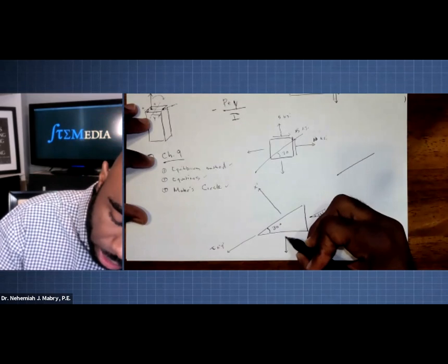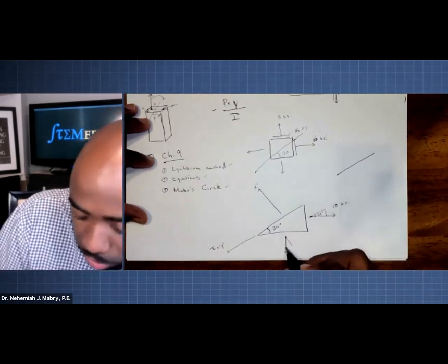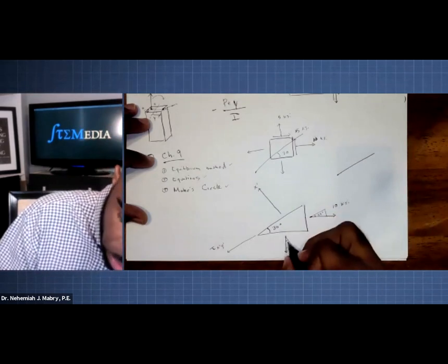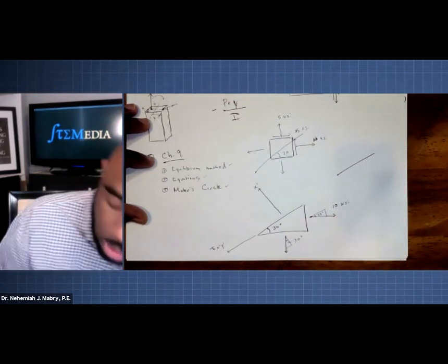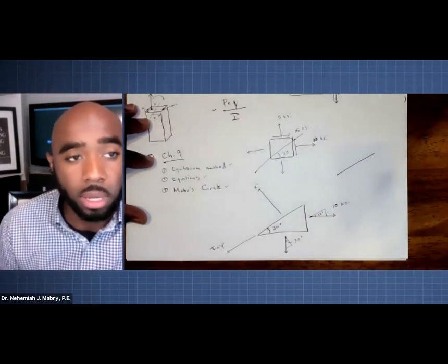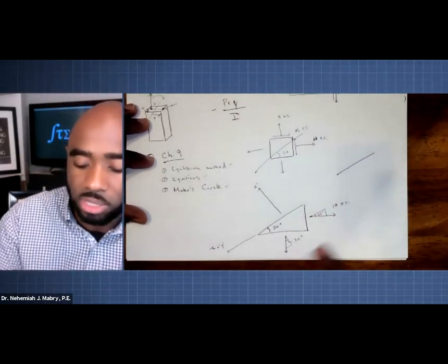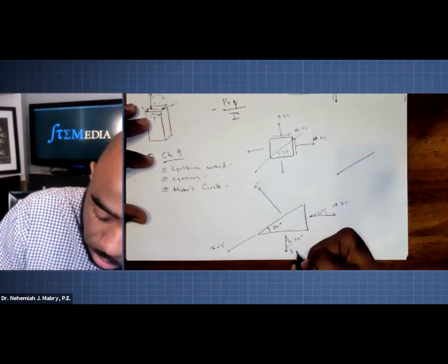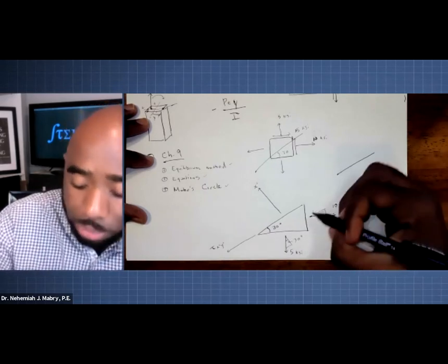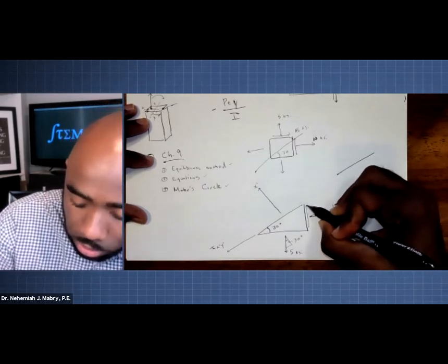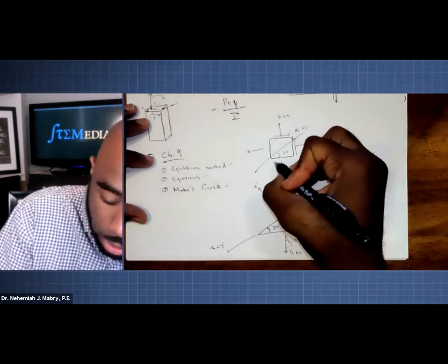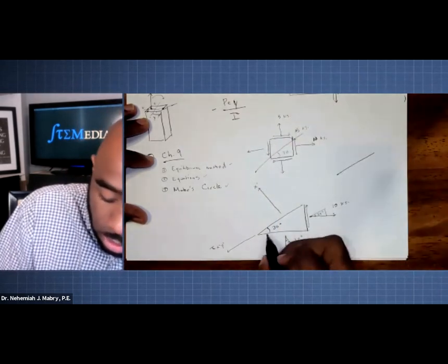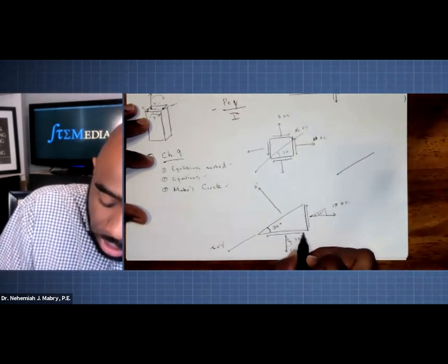But to reorient it, you're going to have to keep in mind that this angle here, or that angle created, is 30 degrees. Just so you can be comfortable changing the orientation of what we were originally given in the problem. The same thing goes for the stress here. And this is just to finish drawing it. And for this shear stress here.